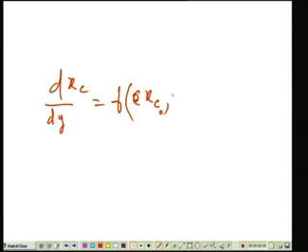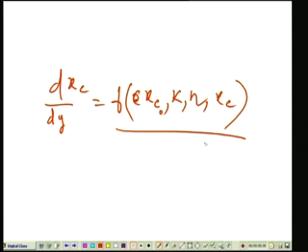say the hydraulic conductivity K, porosity at different points, and the total distance of travel, which is xc itself. So here it becomes a differential equation which is much more complex, considering the plume characteristics.